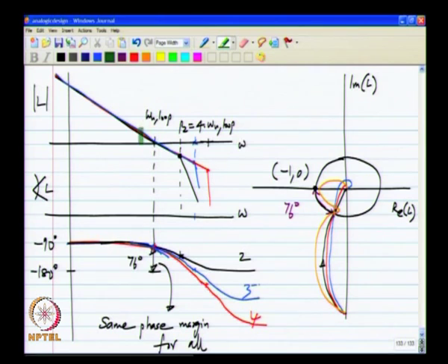But most of the systems that we deal with will not do this, and this is something that you have to watch out for. In the magnitude response, you should not have a case where you have something like this and then the magnitude is close to unity and the phase angle increases. If you do that, you will end up with a system that has a lot of ringing, but usually we do not encounter this particular case. So, we just ignore that one.